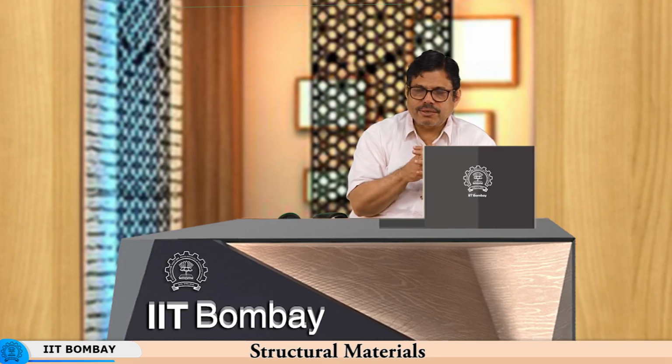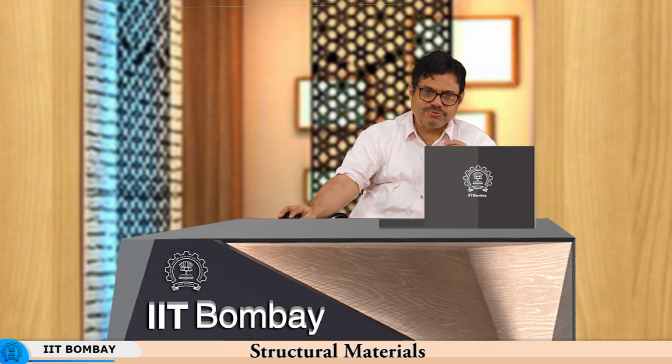And martensite, by virtue of its relatively low fracture toughness, would result in quenching cracks being generated, and the grain boundaries being the ones where most of the cracking would take place, because this is a region of large amount of disorder. Now this defect cannot be corrected, because once the material has disintegrated, you cannot do anything about it. Once the cracks have formed, you cannot do anything.